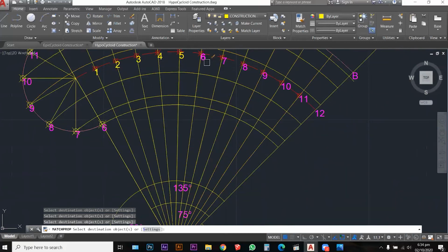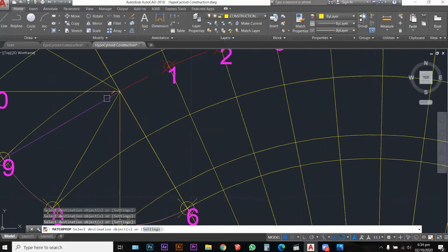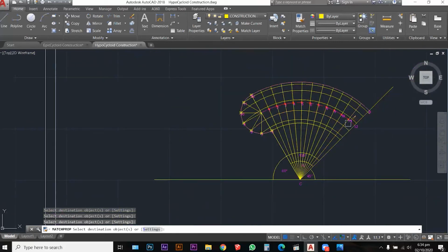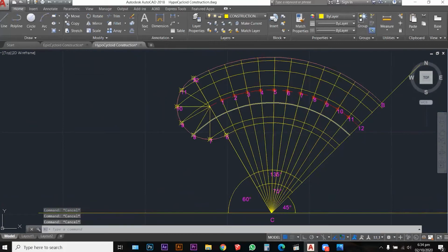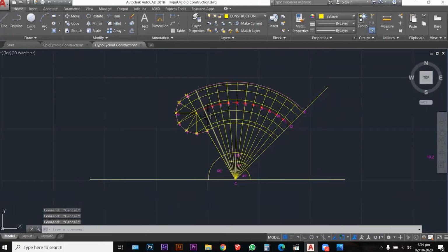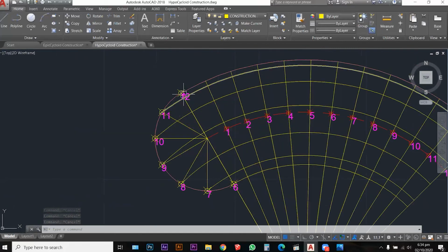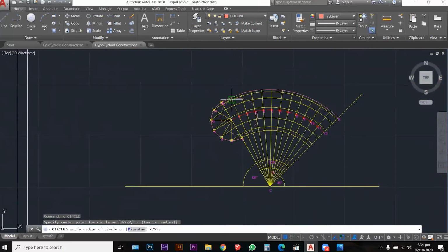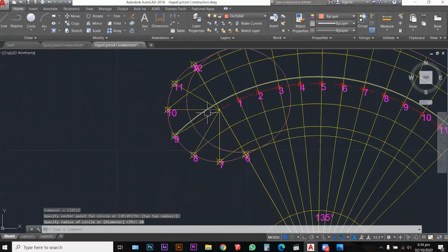I have to roll the circle from point 0 all the way to point 12, and then plot the course. So we are doing an epicycloid, and that means I'm going to create a circle now on my outline layer. I'm going to create a circle at point 1, and my circle is radius 20. I remember that. I'm going to track that point there.